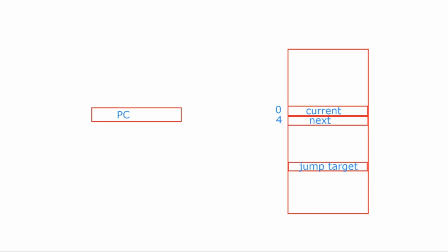So the address of this jump instruction should also be a multiple of 4, say 32 or whatever, because each instruction in between consumes 4 bytes. The 26-bit address is a word address. It refers to the number of words that the PC should be advanced, not the number of bytes.